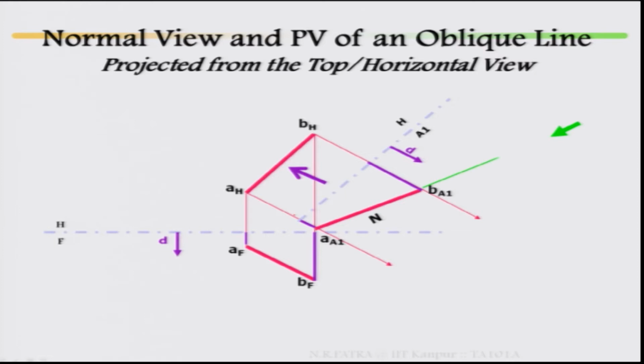Then go to your line of sight with these directions. It is a parallel line of sight, it is not perpendicular. The way it was looking earlier, your line of sight is perpendicular, here the line of sight is parallel to your true length. Then draw auxiliary plane A2, then measure the distance of your opposite top view.